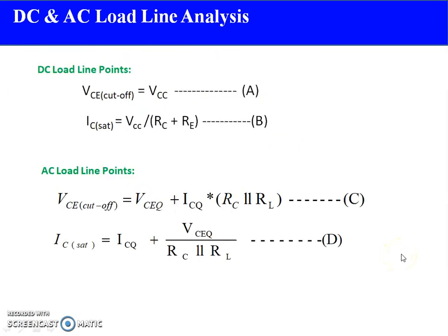So finally, up to this point we have studied DC analysis and AC analysis. From the DC analysis, we concluded two points: VCE cutoff is given by VCC.